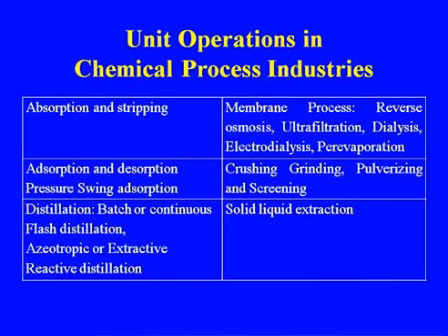That was the development in the case of adsorption, and now the separation of air is possible, because earlier we used to have the liquefaction of air for getting oxygen and nitrogen. Now with the coming of pressure swing adsorption, we are able to produce oxygen and nitrogen even at a lower capacity. Distillation, that may be batch or continuous, flash distillation, azeotropic, extractive, and the newer development is reactive distillation, where the simultaneous reaction and distillation both are taking place.